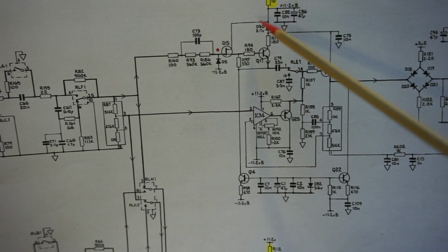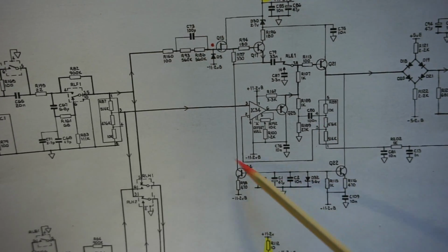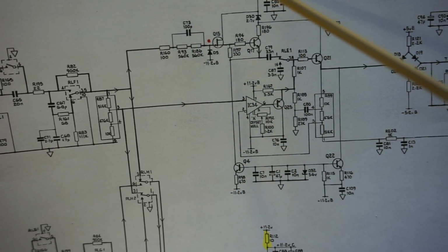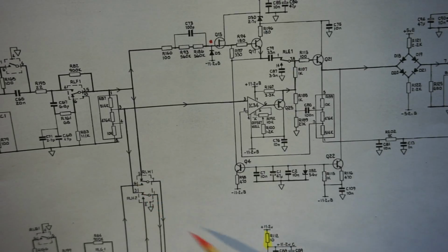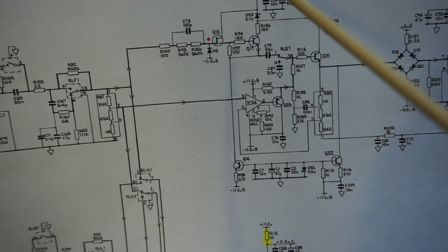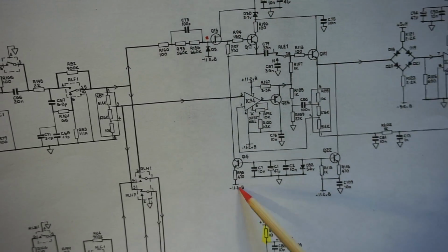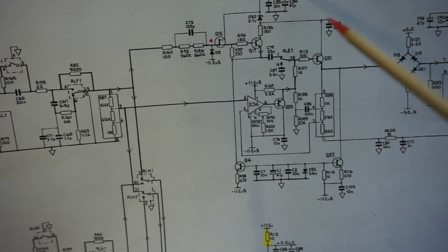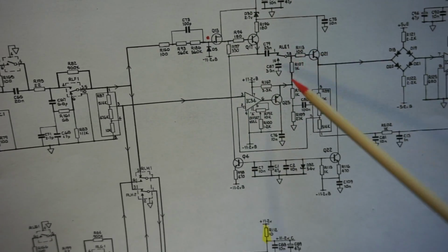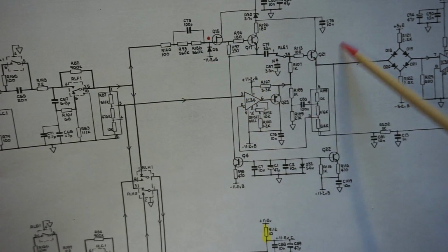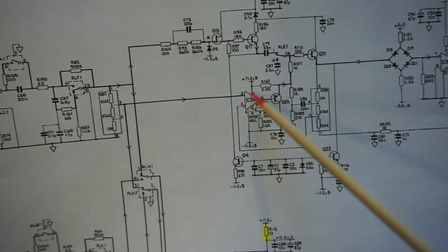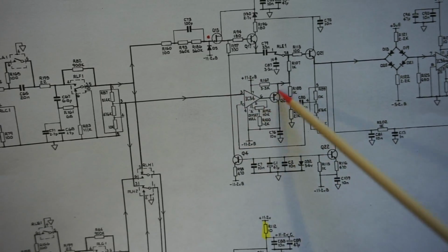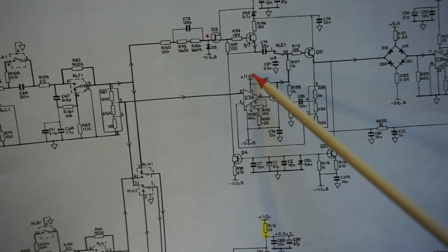And surprisingly, if I measure every single component, it looks fine. For example, with respect to ground, the resistance seems to be normal. However, if I measure directly between the positive rail and the negative rail, the resistance is very low. So that made me shift my concentration from those individual discrete components back to this IC. The reason is this is the only active component that is powered from both rails.